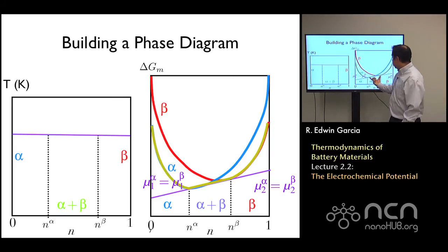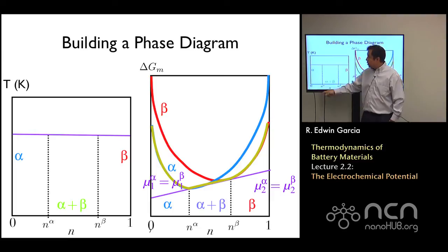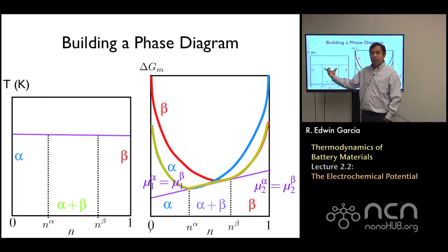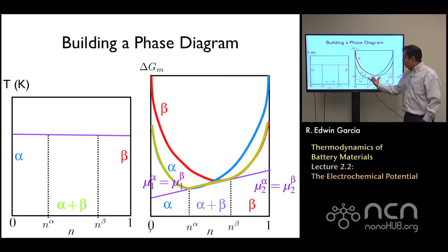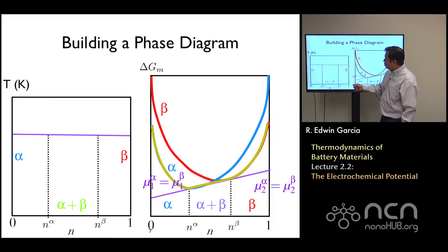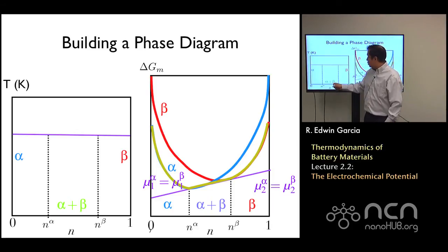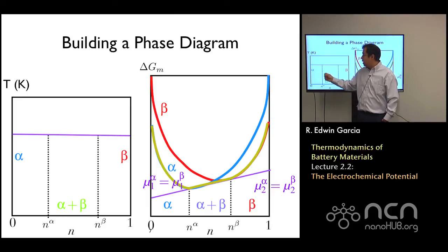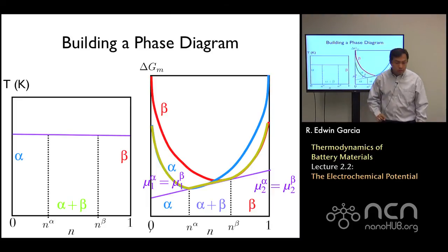These two points specify two points in this temperature versus composition map, so that if I heat up or cool down my sample, it will make these two points move up or move closer to each other, or spread out, basically go away from each other. In that sense, this gives you a direct comparison of how this free energy description corresponds to regimes where alpha plus beta coexist, and specifies how the potential will vary in each compositional versus temperature regime.